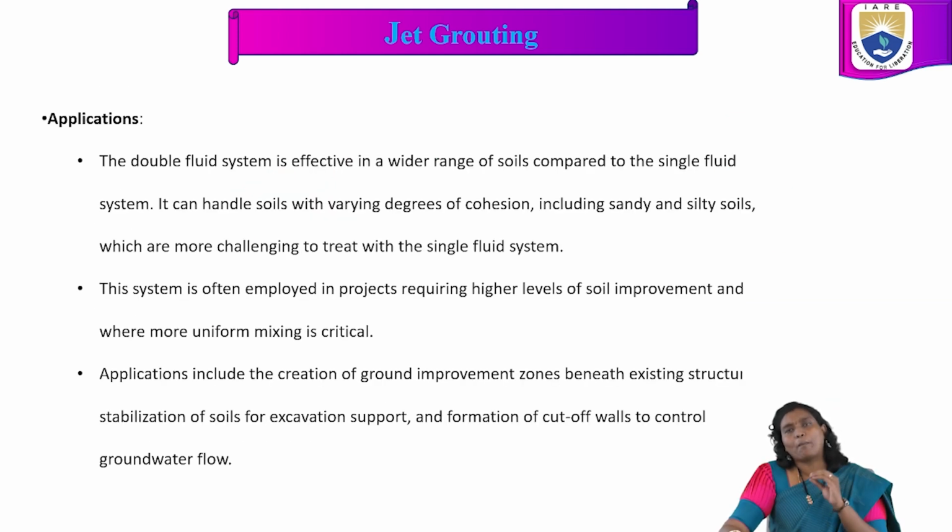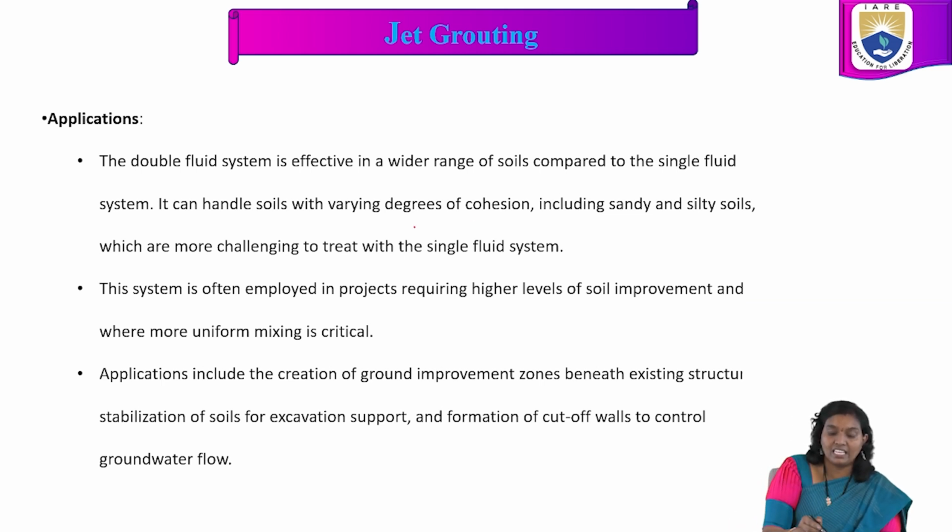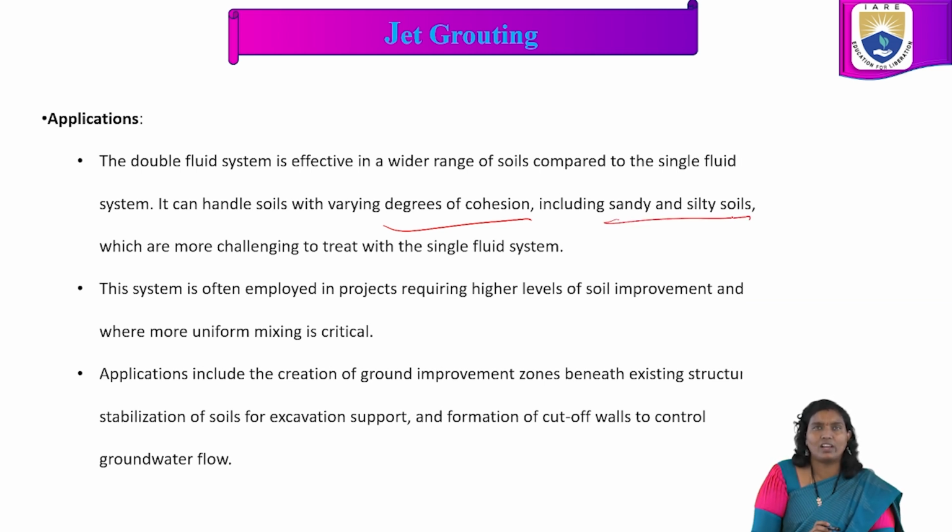Where are we going to apply this double fluid system? The double fluid system is effective in a wider range of soils compared to the single fluid system. It can handle soils with varying degrees of cohesion, including sandy and silty soils, which are more challenging to treat with the single fluid system.